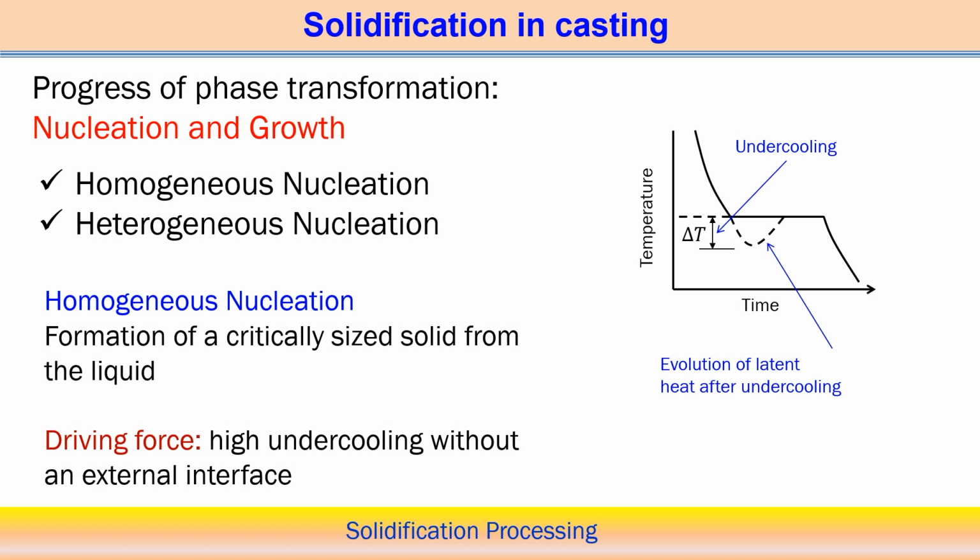So, that is the basic theory associated with the homogeneous nucleation process. Degree of undercooling: we understand that this is the equilibrium solidification temperature. Now, at a certain localized position, this temperature can reduce below the melting point temperature. So, at this particular temperature T and then the melting point Tm, the difference between these two is basically known as the degree of undercooling. That occurs during the solidification.